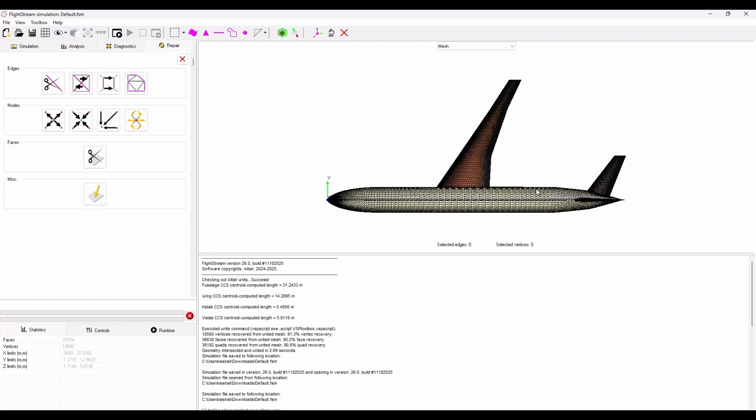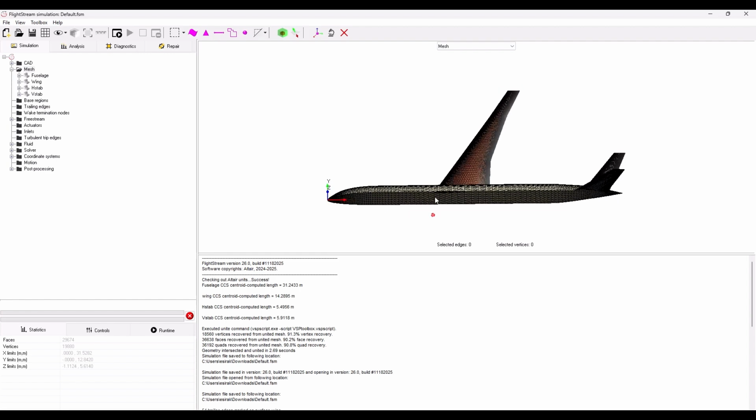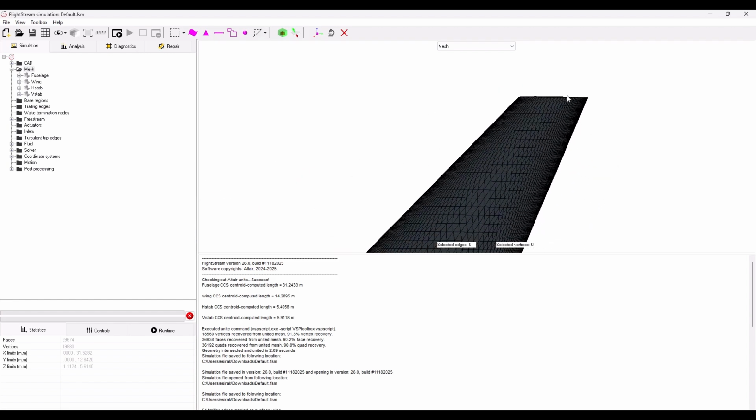Then, in the Mesh dropdown, choose the Select Mesh Faces by Threshold option. Here, we'll use the threshold parameter in Y for a plane at 0, and then the threshold logic will be set to below, and we'll toggle on the Delete Selected Faces option.